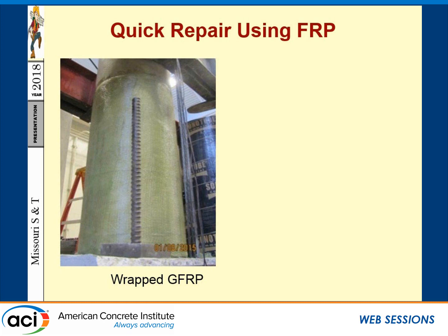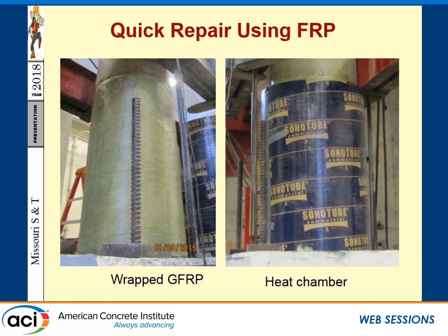In a typical scenario, per the manufacturer's recommendation, you need 1 week of curing for the epoxy resin after you apply it. Well, MoDOT would look, if you have an earthquake, you would like to have an immediate opening for a bridge. So we're looking for rapid retrofitting. So to accelerate the retrofitting, we ran a lot of small-scale testing and analysis on the epoxy to accelerate the curing of the epoxy.